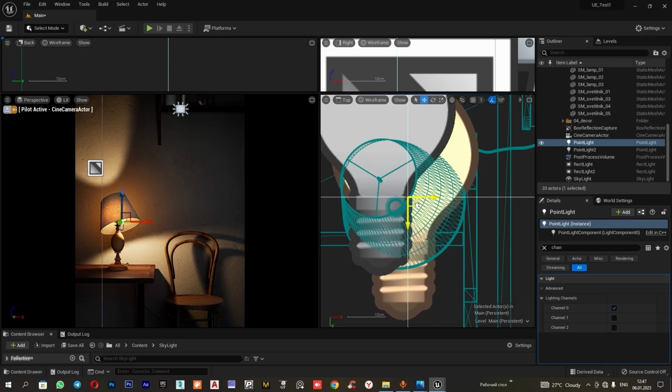Now I'm satisfied with the lighting. Currently you may notice some slight shadow roughness, which might go away when we calculate the sequence. Everything is fine for now. If there are any other artifacts, you can enhance the light quality at the light source by going to Samples per Pixel. Select the light source, Samples per Pixel, and adjust the value higher. Avoid setting significantly high values as it affects performance.